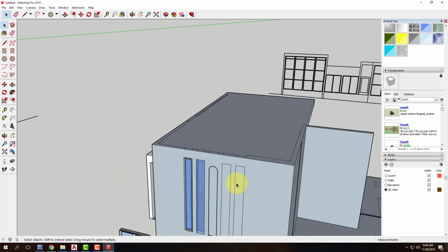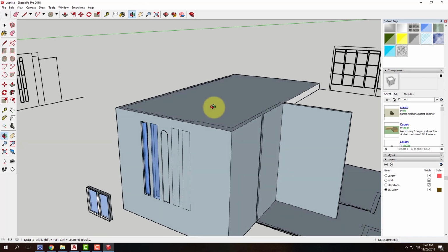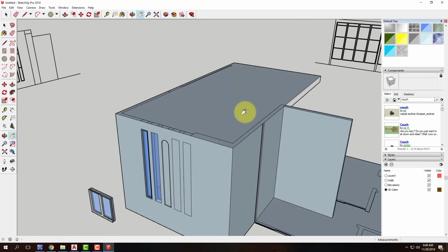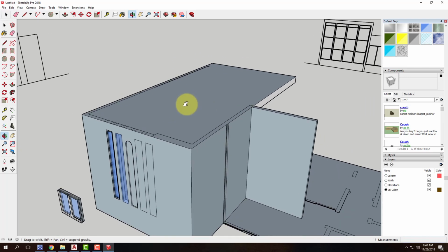Are there any other questions, anything specific that anybody wants to know going forward? Yeah? An easy way to pan. I've always just scrolled in and scrolled out. There is a pan tool right up here at the top. I know your middle mouse is orbit. Shift and middle mouse. Hold down Shift, and it will pan. Thank you for that. Truth be told, I don't model much in SketchUp. I model in Rhino, so it's just me.